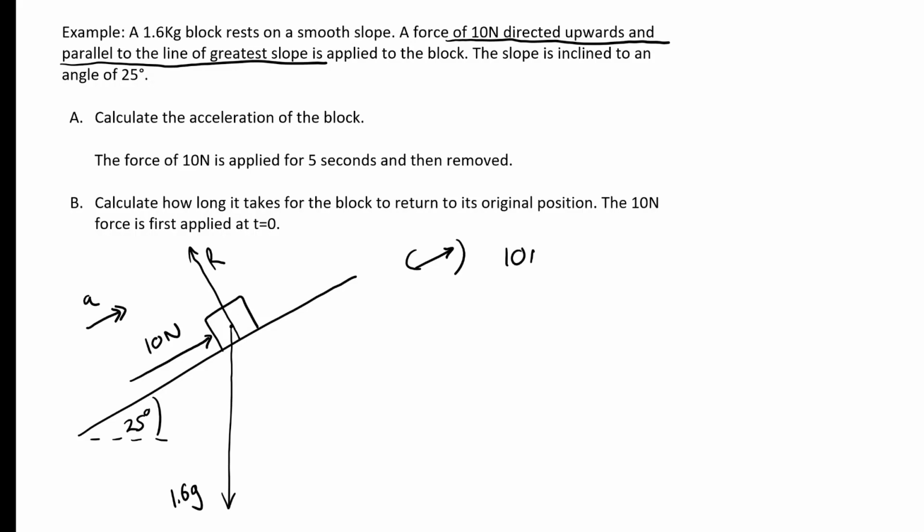So we've got the 10 Newton force. It's fairly clear to see that that force follows this arrow, the one we've decided is positive. And we need to break the weight down into two components. So we've got this green component, which is how much the weight presses into the surface. It's the perpendicular component of weight. Then in addition to that, we have this component of weight that is parallel to the surface. If we move that along, we can see that that's parallel, but it's directed down the slope. So whatever its value is, it will be negative when we put it into this equation we're forming.